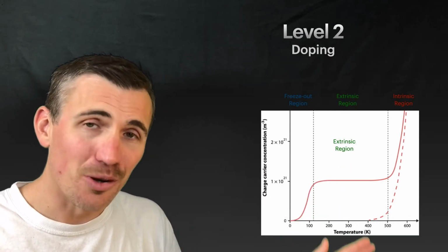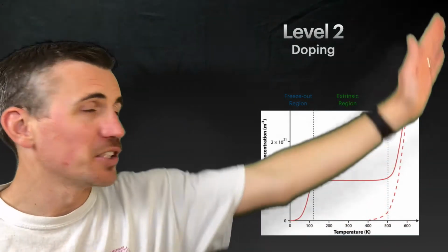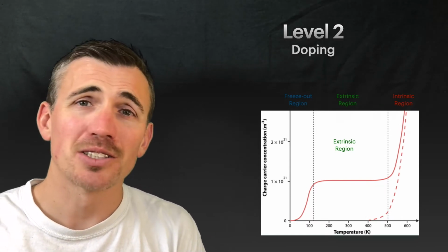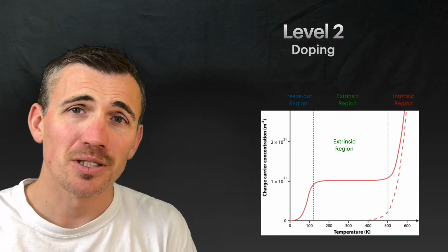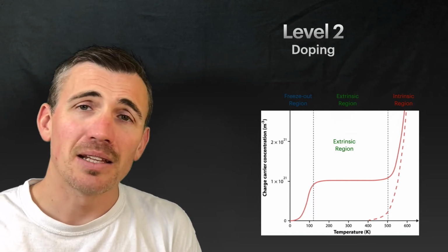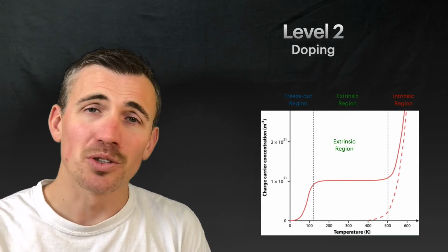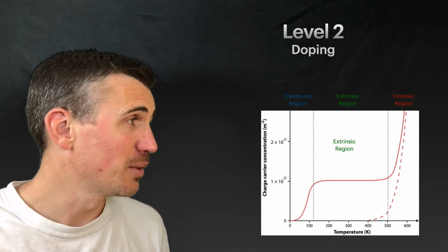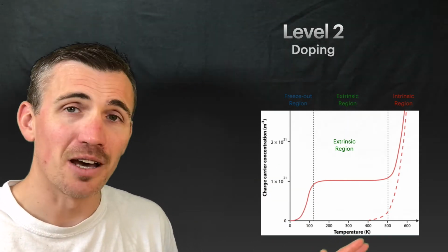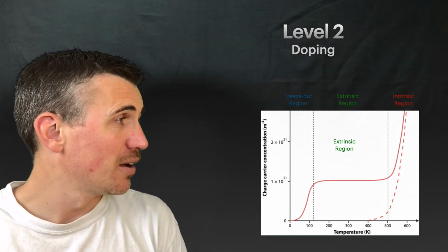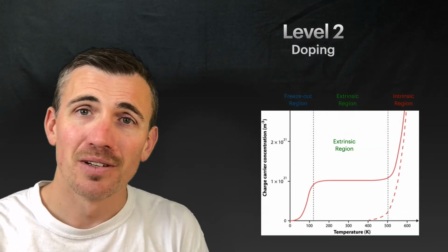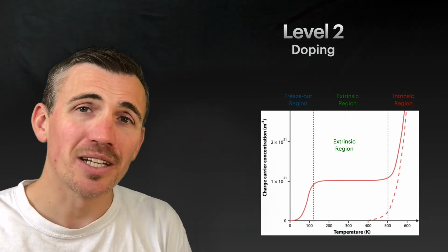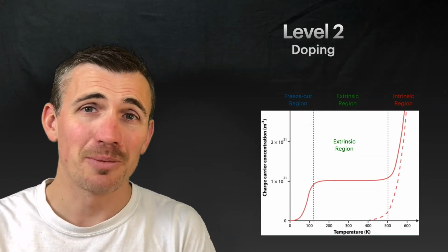And then the thermal catches up, right? It just skyrockets. When that happens, we have enough temperature. We're just knocking so many electrons free from that temperature that even overwhelms the electrons and holes from the dopants. All right? There's only a fixed number of them. And eventually, we jostle the silicon lattice enough, we're going to get more electrons from the lattice itself. And all the devices that we're interested in are going to concentrate in this region here. Okay, and that's how we're going to make some neat stuff.